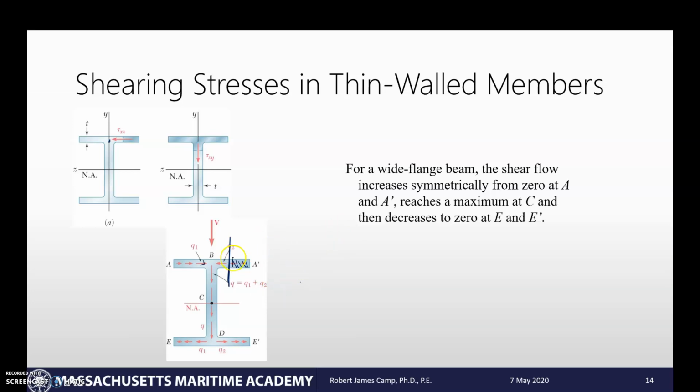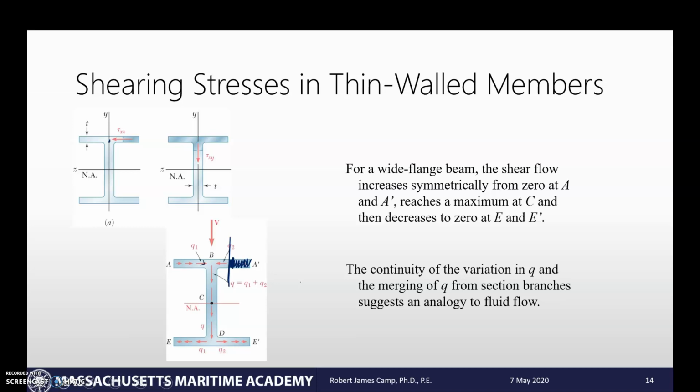The thing is, this is the only area that's really causing that shear stress in that flange of the beam. The rest of the beam's not causing any of that shear stress, it's just that area there. So we're just looking at this little section of it, and it's not the entire top of the beam. And so it varies, it comes together. Once again, it's still at the neutral axis. It's going to be maximum.